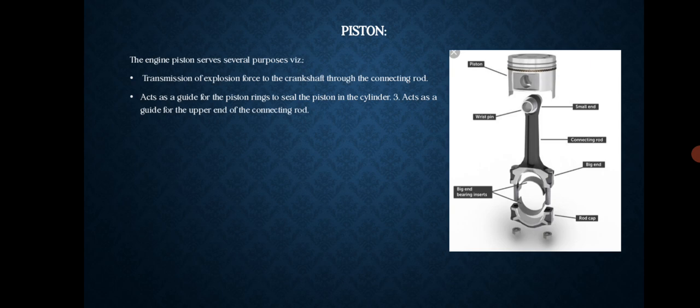Piston. The engine piston serves several purposes: transmission of explosion force to the crankshaft through the connecting rod, acting as a guide for the piston ring to seal the piston in the cylinder, and acting as a guide for the upper end of the connecting rod.